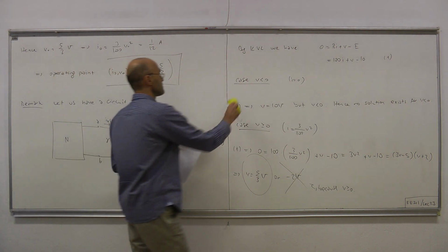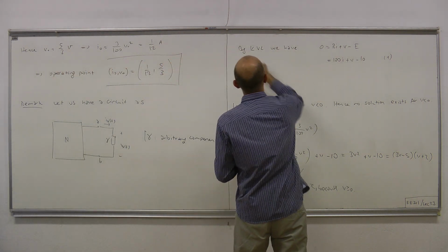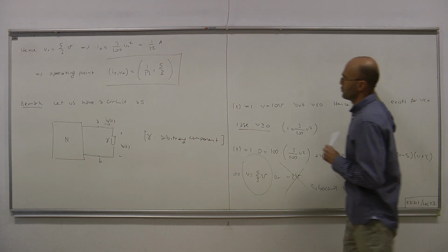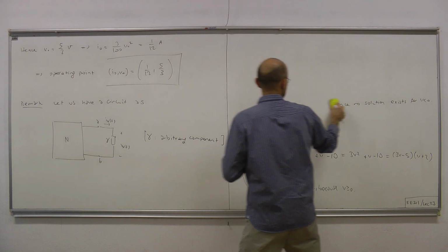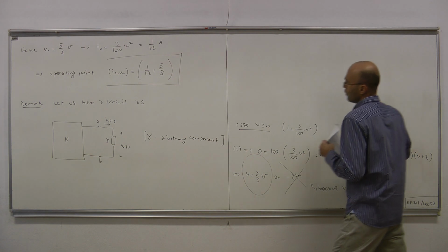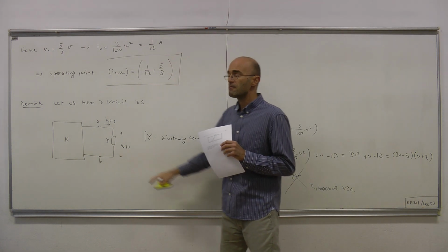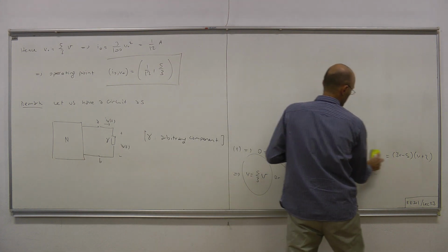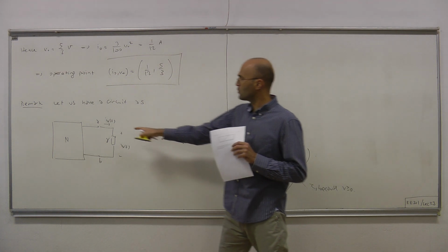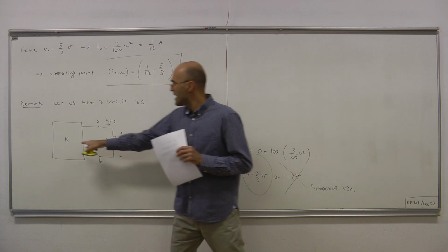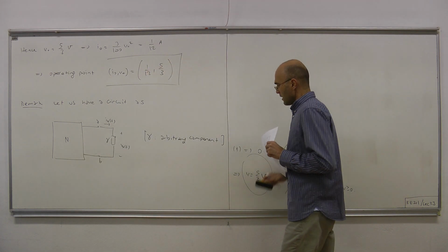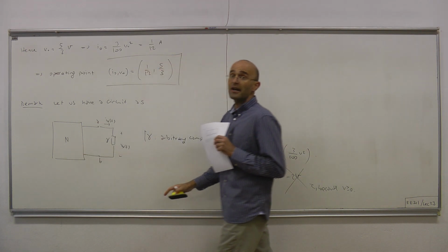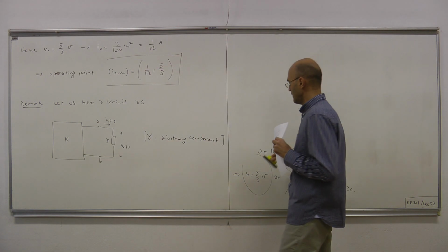Now then, by the substitution theorem, you can replace that component by an independent voltage source that provides voltage that equals Vx of t, or you can replace that component by a current source that provides current that equals Ix of t, and within N, everything will still be the same. In other words, an observer sitting inside N will not be able to tell the difference.